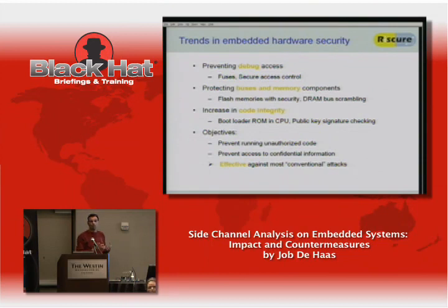So these kinds of attacks become harder because you need to physically open your device much deeper by opening up the PCB itself, or taking away hard epoxies or things like this. They don't really prevent the hardcore deep first time attack where you spend a lot of time. That's something these attacks generally won't prevent.